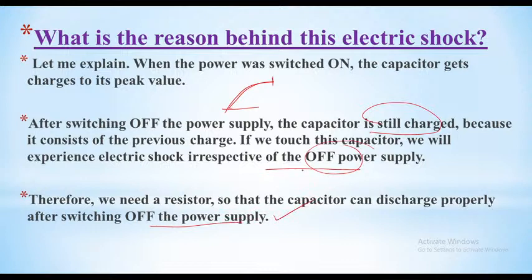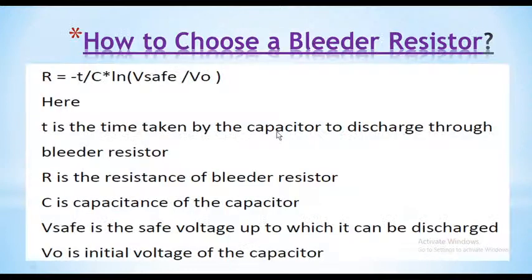Irrespective of the power supply, whether it is on or off, we have to connect the bleeder resistor in parallel with the capacitor in order to overcome electric shocks. So how do you choose a bleeder resistor?